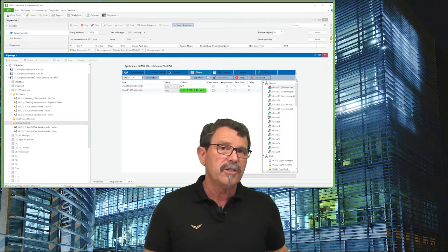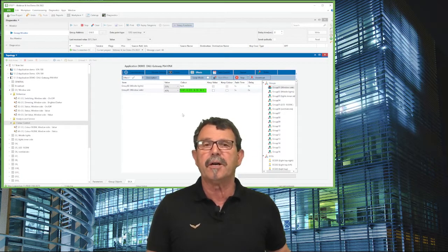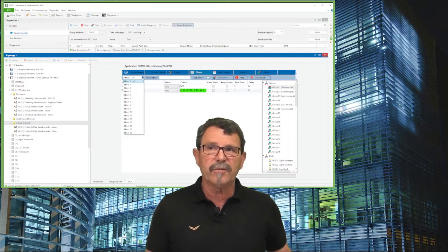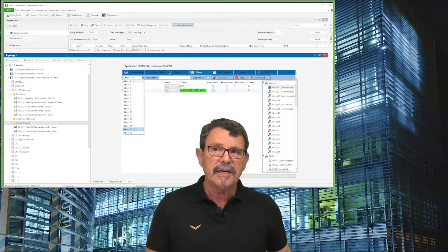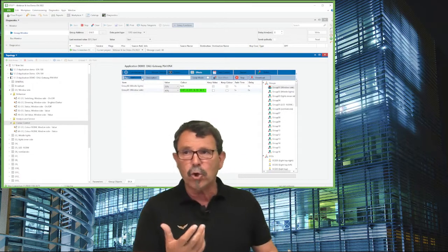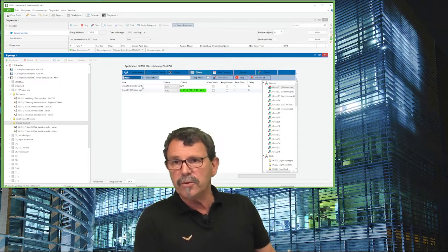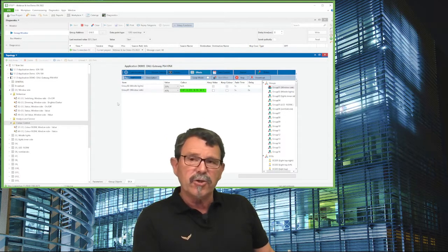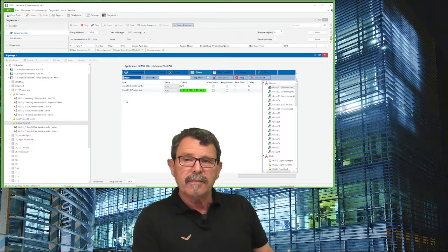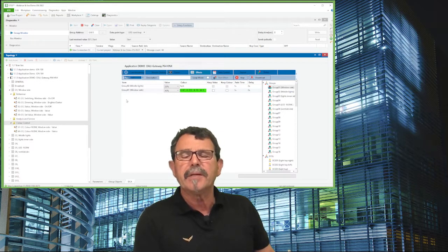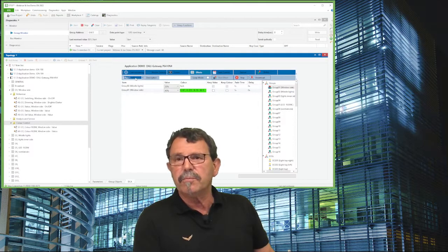So you can just by drag and drop, you put some of these lights here in this effect mode. You can separate it here, for instance, in different maximum 16 effects. Such an effect is finally called up by a value. Effect 1 is value 128, and you stop this effect by sending a 0, sorry. If you want to call up effect 2, means you send 129 and you stop it by a 1.